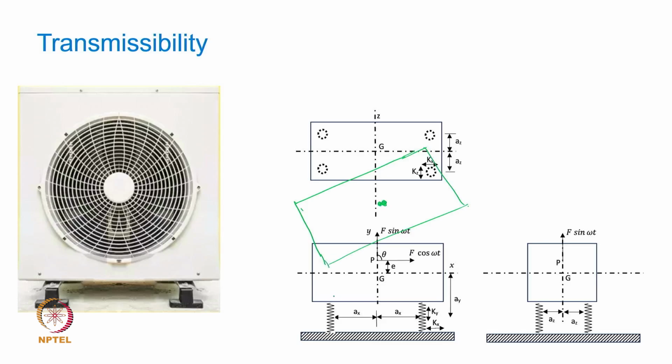So this box moves in all degrees of freedom here, so we have a slightly rightward horizontal motion of the CG. So this CG gets shifted. It is of course shown very exaggerated here, but you will have to presume that this value is going to be small for our linear assumption to be valid.